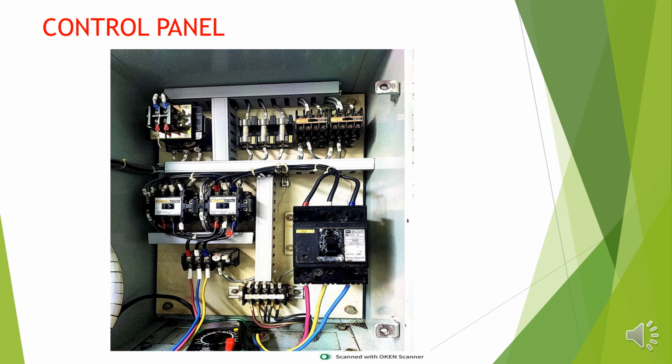So the interlock, I will tell you here. So this is the 88F contactor. For the 88F contactor, the interlock is the 88R. Okay, so you see here, 51 and 52 is a normally close contact. If this is not closed, this 88F will not energize. So why this is not closed, you have to check by using the multimeter, these two contacts. Maybe the contactor has some problem. Okay, so you have to check that.